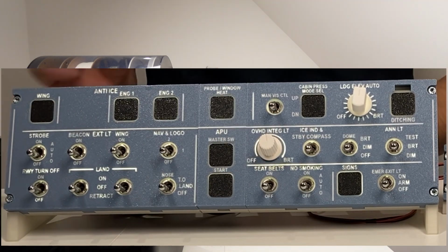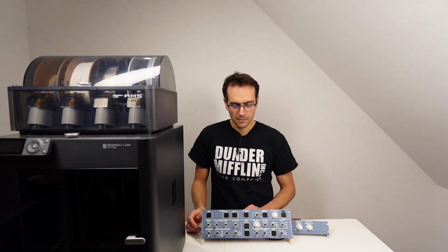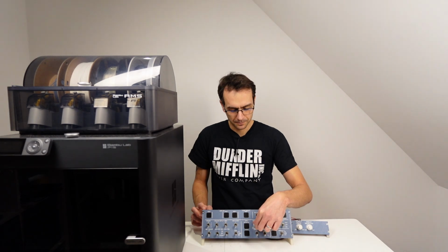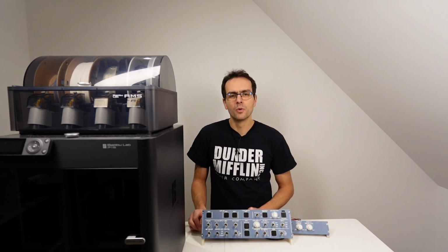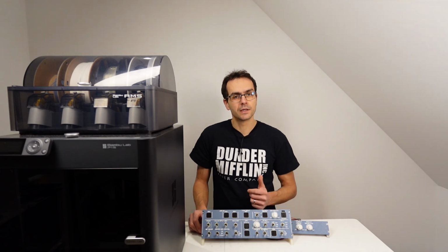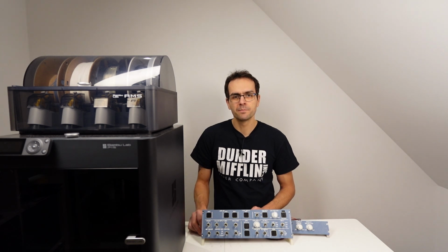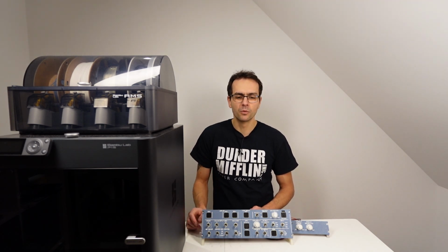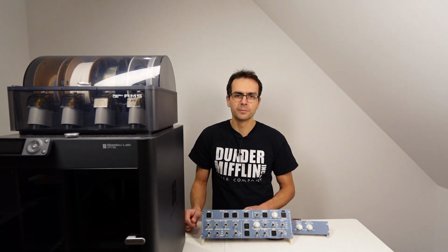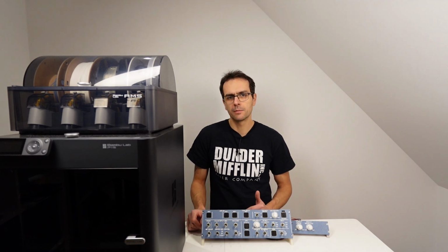And of course, you can just insert some LED strips and provide it with a constant power, but it's much nicer to have it dimmable. And there are basically two ways to do this. The first one is to use LED strips that provide the dimming function already, but then you have to deal with voltages and control the voltage that the LED strip is provided with. And the second one is Pulse Width Modulation, or PWM for short.